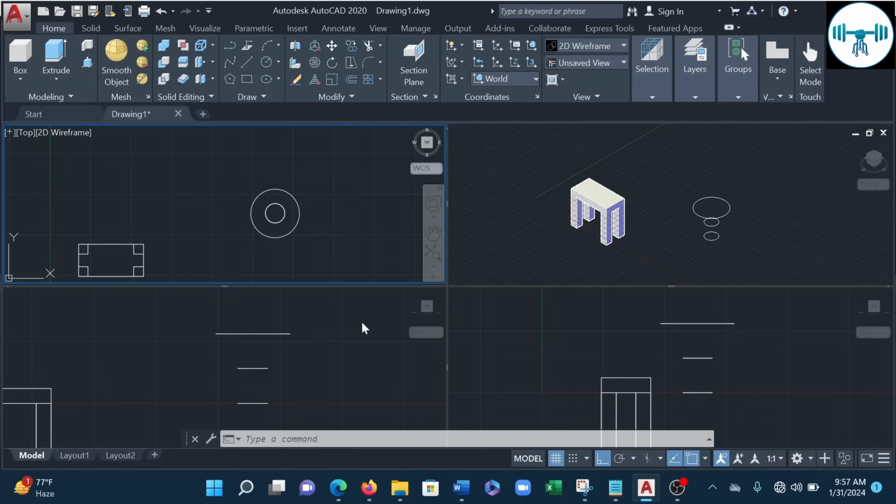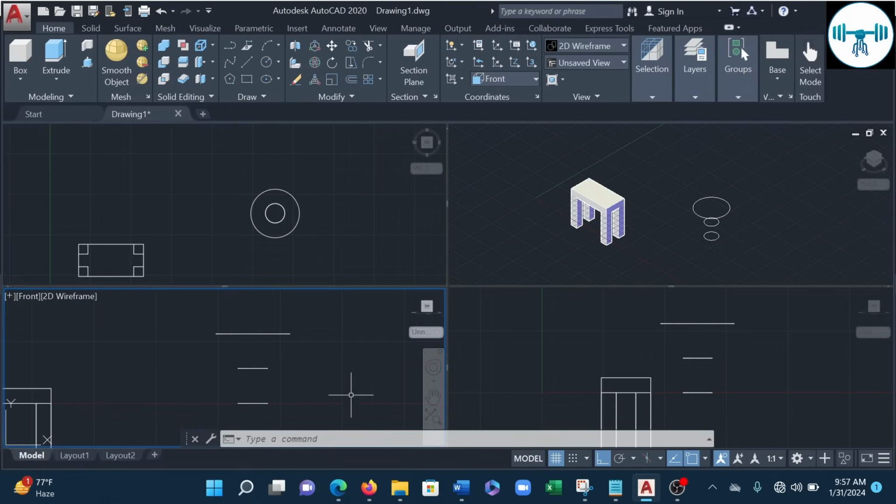And then finally we want to repeat our 15 mm circle with a little height, so that when we are pouring liquid in that top, it doesn't spill. Because it's like a hopper, it's going to hold the liquid, so we're going to put a little height to it. So I come back to my front viewport, select this 15 mm diameter circle that I just drew, and then I'm just going to move through a height of, let's just use 2.